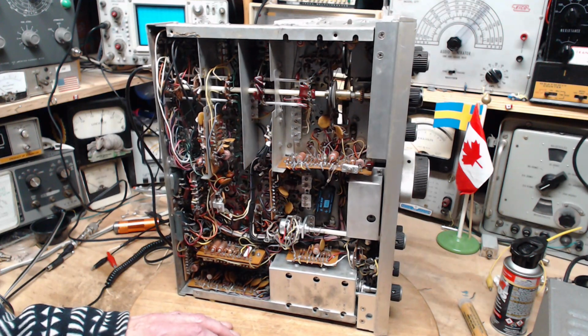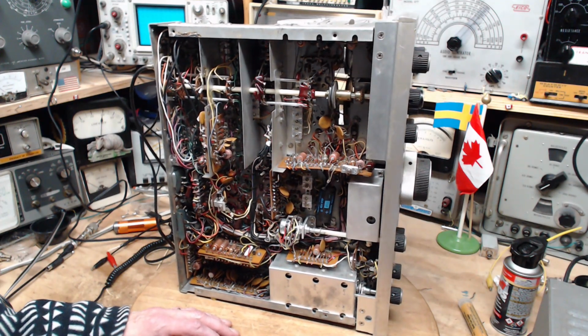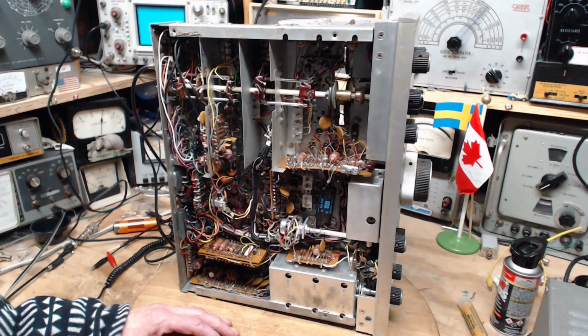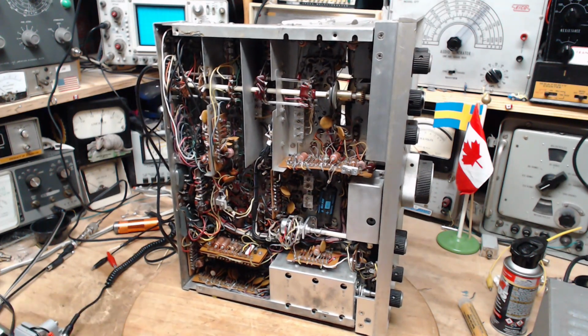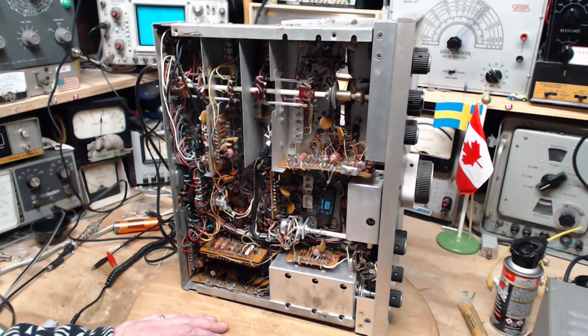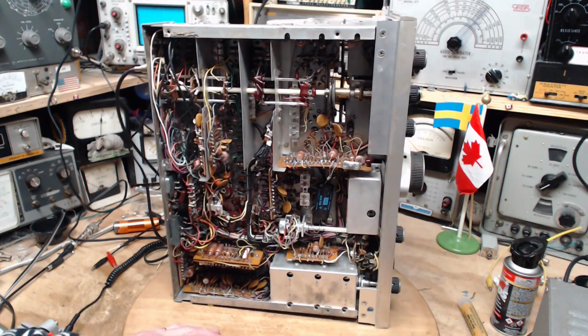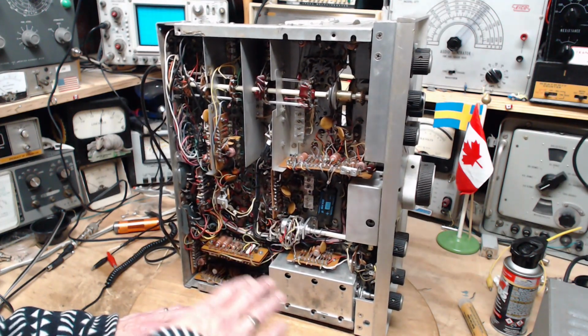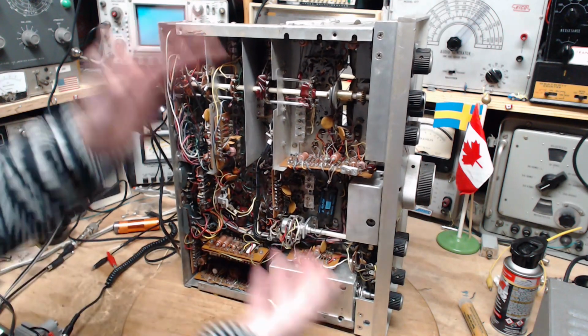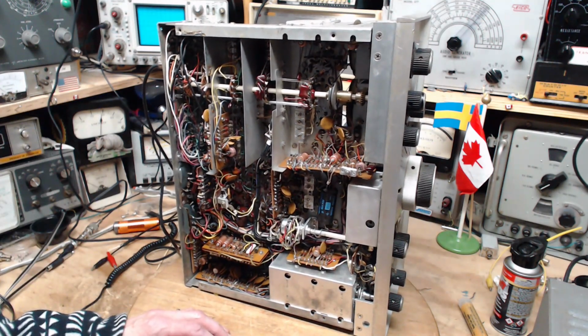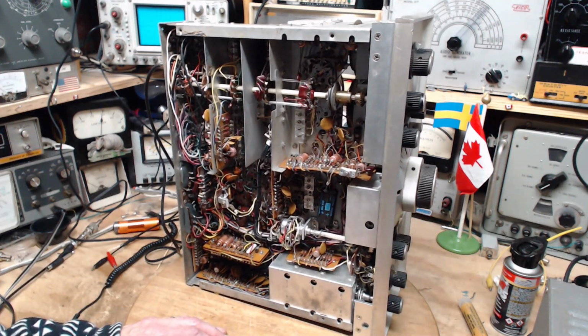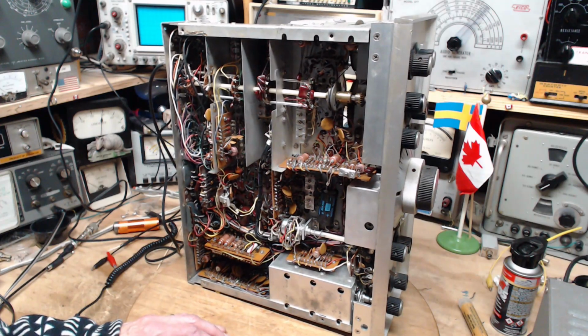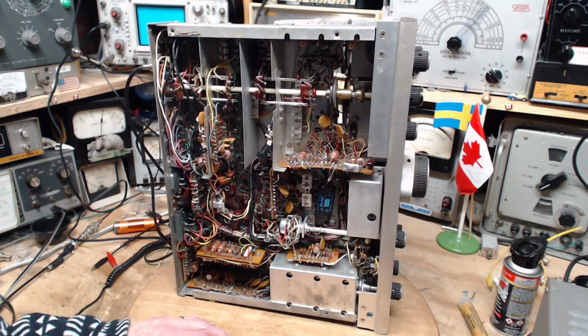And they have a way of fiddling with collector voltage on one of the transistors involved in the 230 kilohertz IF. And this is what mutes the radio. So it actually cuts the radio off quite early. Well, in this radio it's not early, it's actually late. But they cut it way ahead of the audio, somewhere in one of the IF strings.